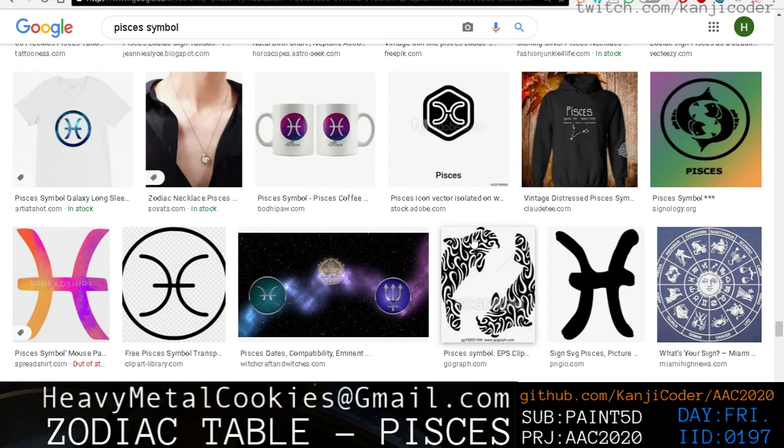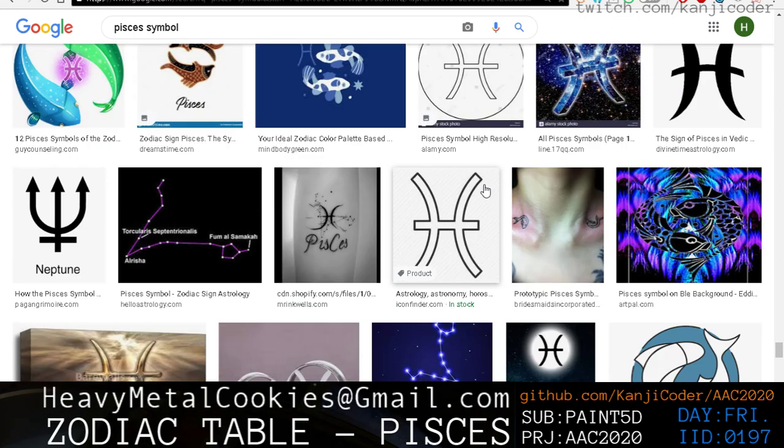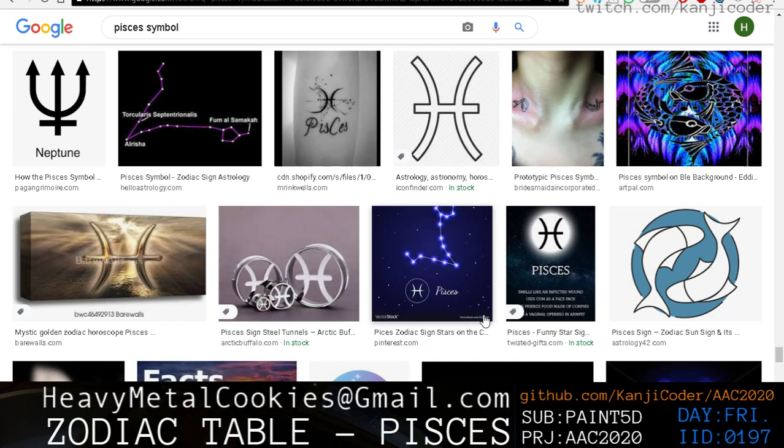So I'm thinking if we could get away with it, it would be nice to do a 45-45 cut of the semicircle, like creating a pie slice where to create this arc, we go from the center of the circle and we go out 45 degrees here, and then we do the same thing down here. We go 45 degrees this way. So if this is 0 degrees, positive 45 degrees, negative 45 degrees, and we make these cuts on that circle.